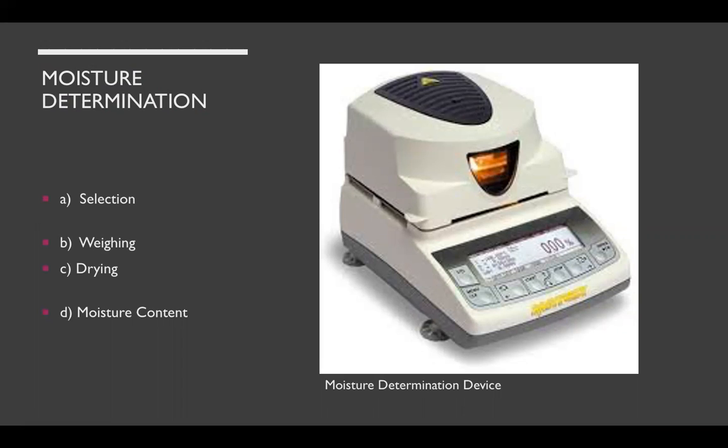So, drying. The moisture sample shall be open piled in an oven and dried at a temperature of 103 ± 2°C (217 ± 4°F) until approximately constant mass is attained, after which the oven dry mass shall be determined. The moisture content, lost mass expressed in percent of the oven dry mass as determined, shall be considered the moisture content of the specimen.